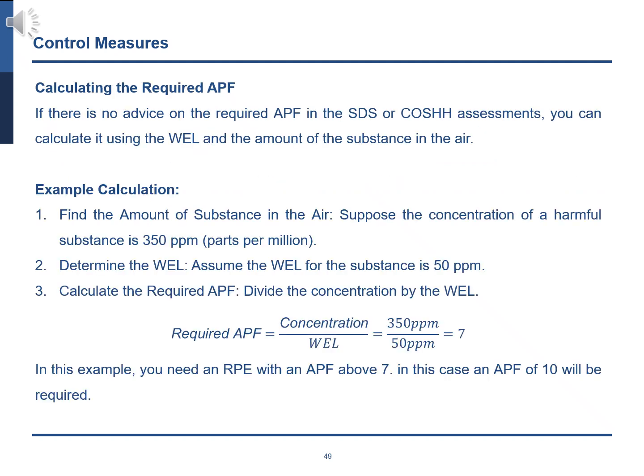Calculating the required APF. If there is no advice on the required APF in the SDS or COSHH assessments, you can calculate it using the WEL and the amount of the substance in the air.